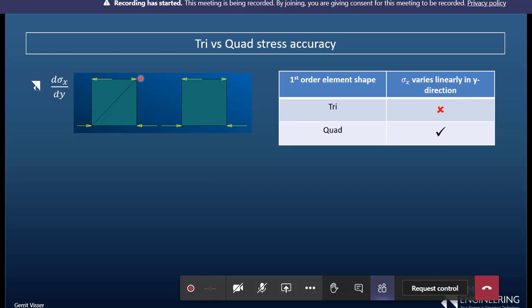It will say there's a zero stress. There is some stress, but it's not very high because it's this average tensile value. Again, zero because it's averaging a tensile and a compressive value that's about the same. And I'll get a compressive value at that location. So I'll get a pretty weird stress distribution. For this element, after applying that load, I'll see that linear stress distribution through the thickness. So it's going to be pretty close to what it's supposed to be.